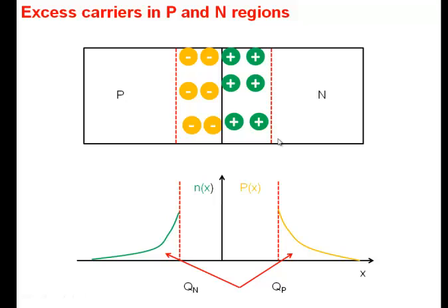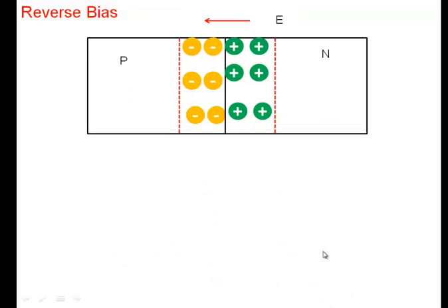So note that there are two distinct sets of charges in a PN junction. One is the depletion charge, and the other is these mobile charges, or diffusion charge, on this side and this side. Both of these change as a function of voltage, and therefore that change manifests itself as a capacitance. That results in diffusion capacitance. So there are two distinct capacitances in a PN junction.